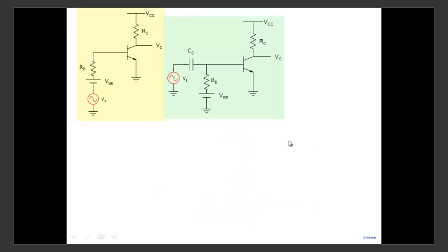So if you recall, last lecture's discussion, the traditional discussion of amplifier, begins with a circuit like this, where we use a battery with a resistor RB, and along with the resistor here and a source here, we bias it in the forward active mode, and then we attach a signal here, which we want to be amplified and appear over here.